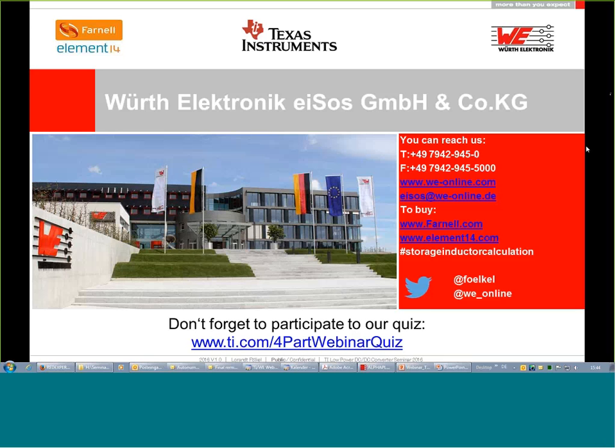There is a disadvantage as well: the saturation is not as good as an open magnetic field rod core inductor, because the unshielded version is like a vertical rod core to the PCB, and because it can have an infinite air gap, its saturation is much better. That's the advantage. But the disadvantage you will see in the EMI measurement chamber, and you will see it in the RDC. For a filter inductance, you can use a non-shielded inductance. There's no problem, but not for storage.